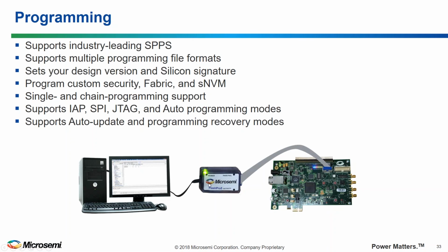And that Flash Pro allows you to program the device, and then you can also use that if you're using SoftConsole to download code to your board if you have a design that uses a soft processor like a Cortex M1 or a RISC-V, and you can develop your code. Okay. And then this other one is a good question.